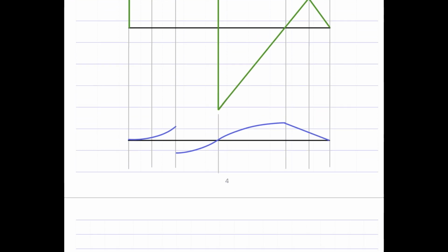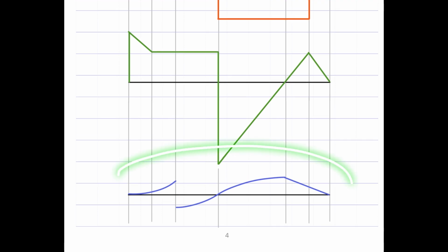And I'm also showing the deflected profile, which is interesting. Okay, one can also check this here. So as you have a shear release here, this gap is seen here. Okay, this is a fixed end, so the slope of the deflected profile is zero here. And then you have an internal release here, which means you should have a slope discontinuity in the elastic curve here. All right. So you can check this deflected profile as well. One can relate this deflected profile to the bending moment diagram. Okay. One can do that and comment in our video.